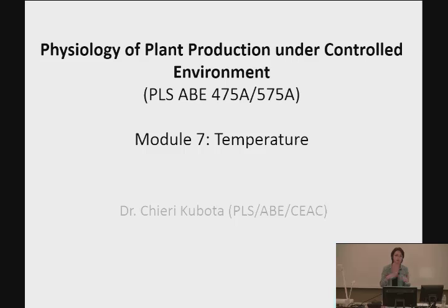I got questions from some of you asking about the efficacy of vertical airflow in a greenhouse relative to horizontal airflow. Yes, if you are willing to maximize photosynthesis, vertical airflow is probably the way to go rather than horizontal airflow. But right now, the priority is temperature uniformity, and that's very important too.